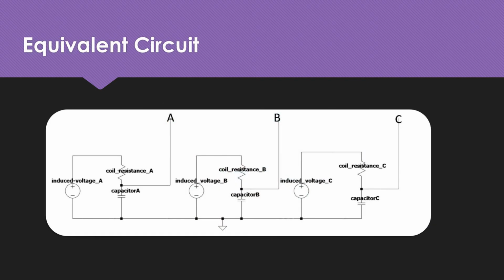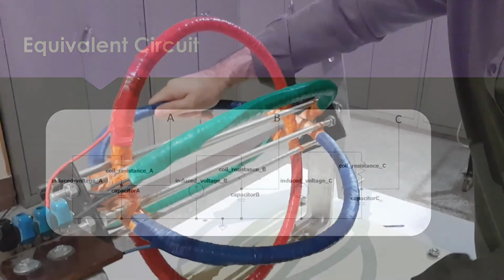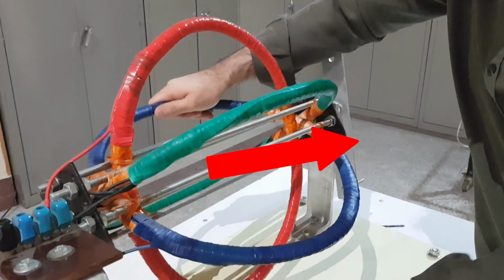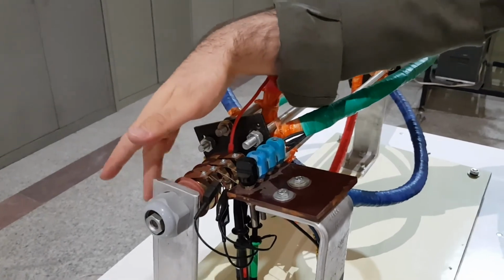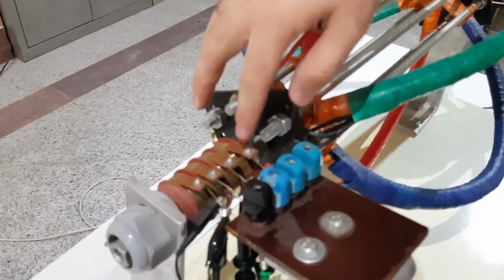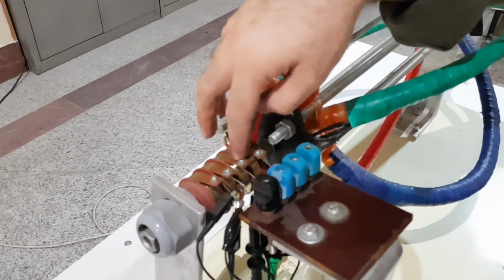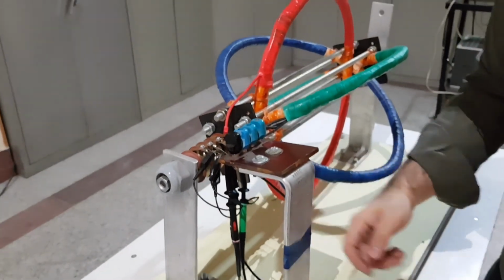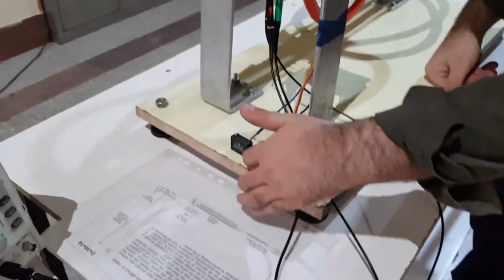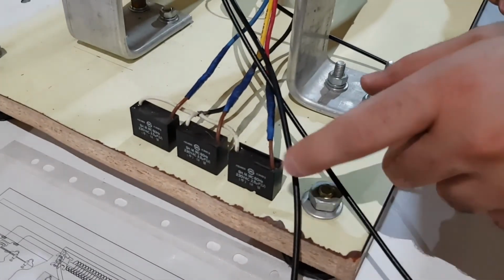Here the equivalent circuit of the 3-phase generator is shown. We will measure the voltages of the capacitors with an oscilloscope. Here you can see a 120-degree angle difference of the 3 coils. The 3 coils have a star connection, and here you can see 4 slip rings, 1 for the common end and 3 for each phase. And here you can see 3 capacitors, one for each phase.